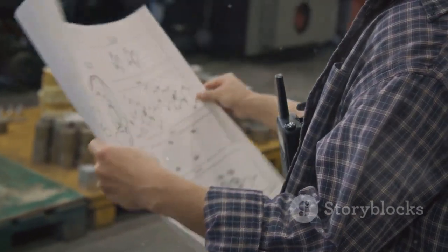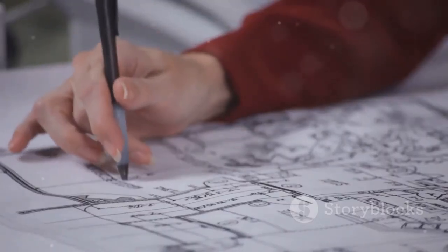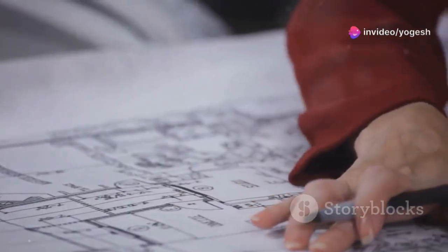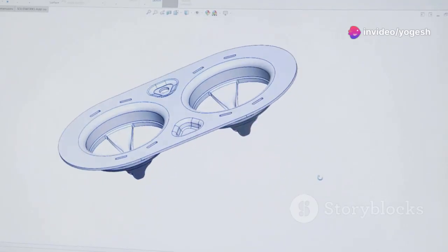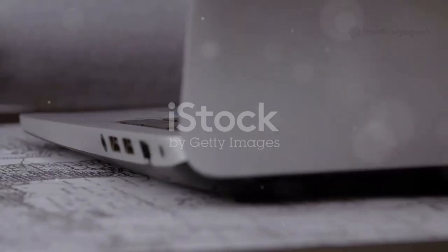Reduce cognitive load for the machinist. Use GD&T callouts for internal features. Connect tolerances directly to features. This ensures the final part functions as planned. Clarity and precision are key.